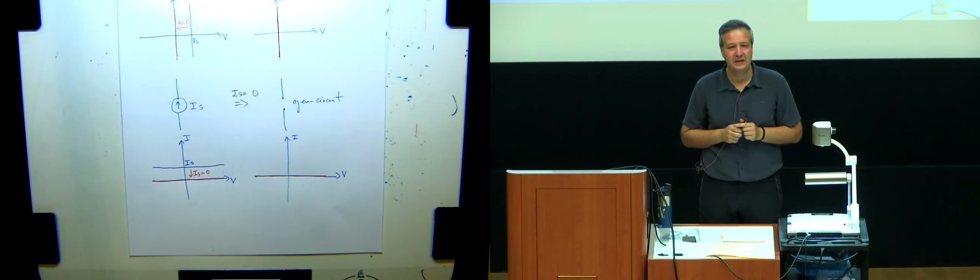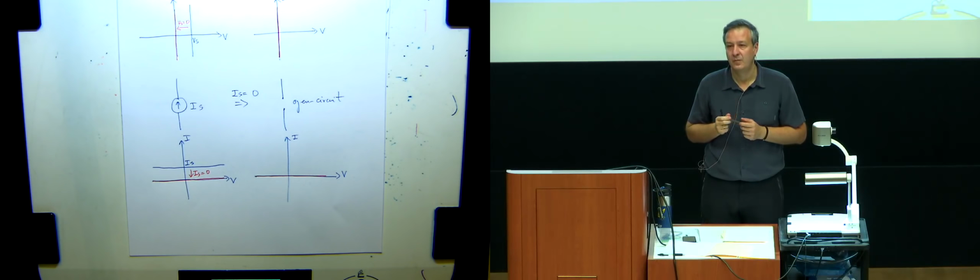Starting to get an idea? Any ideas? Yes? You can replace all the voltage sources except for one with wires, all the current sources with open circuits, and then solve for specific components of the system, like you had to do for every other element.